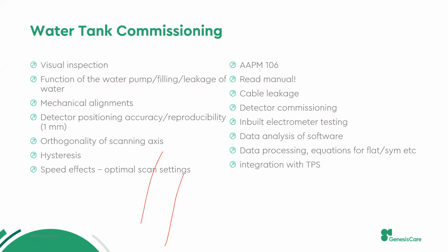If it is making some ripples, then there is hysteresis, meaning it's vibrating. So that's the simple test that those motors are really moving your chamber smoothly without any hysteresis. Okay, thank you. Why is this happening?